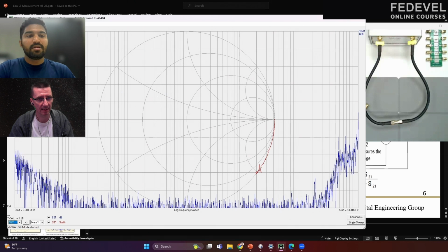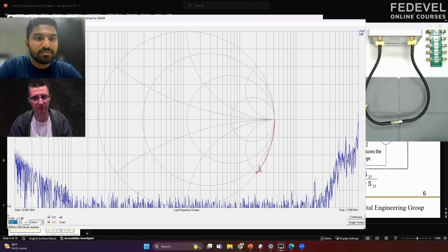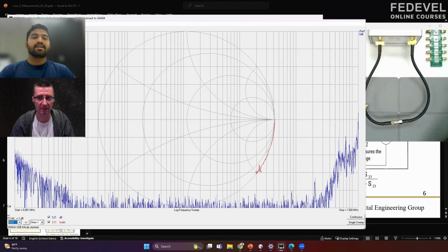And so basically, once it is calibrated correctly, for example, if we use the 50 ohm termination or anything else, then we should see the specific results, like around 50 ohm results, for example. Exactly. That's the next step that we will do here.